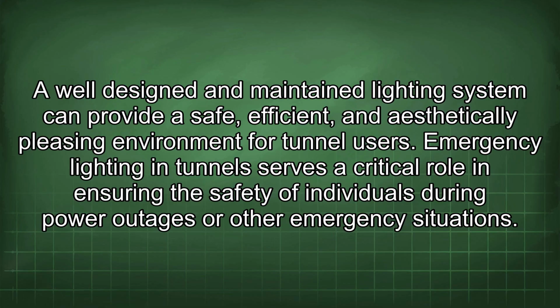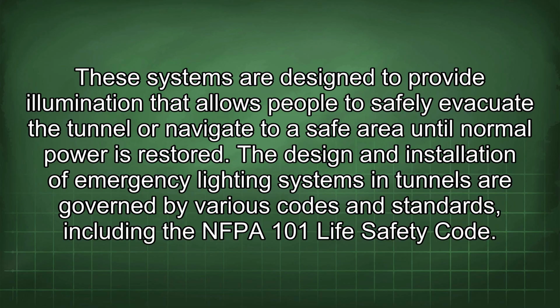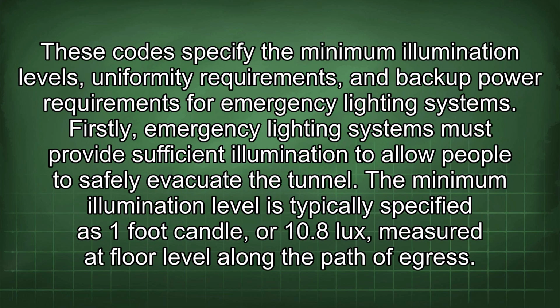Emergency lighting in tunnels serves a critical role in ensuring the safety of individuals during power outages or other emergency situations. These systems are designed to provide illumination that allows people to safely evacuate the tunnel or navigate to a safe area until normal power is restored. The design and installation of emergency lighting systems in tunnels are governed by various codes and standards, including the NFPA 101 Life Safety Code. These codes specify the minimum illumination levels, uniformity requirements, and backup power requirements for emergency lighting systems.